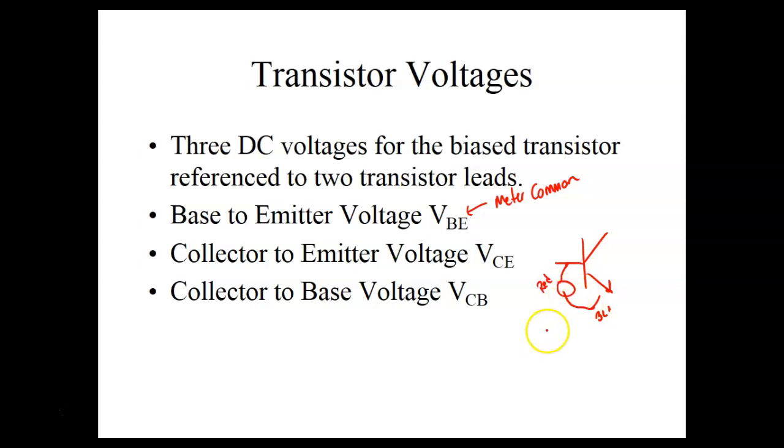When it's forward biased for an NPN silicon transistor, this is going to be approximately 0.7 volts. For a germanium, this should be approximately 0.3 volts. We know that's not perfect. It's just basically a rule that we use in math because it varies with current. Once it conducts, it might start conducting when we put about 500 millivolts on the base.